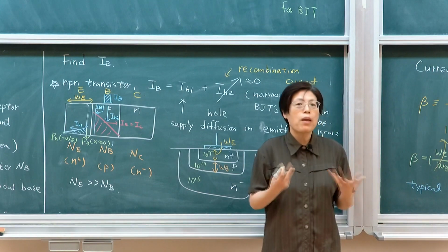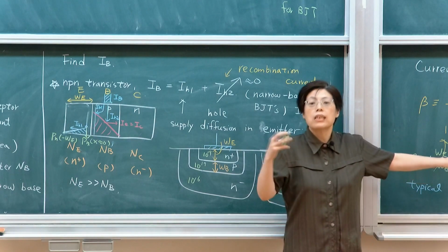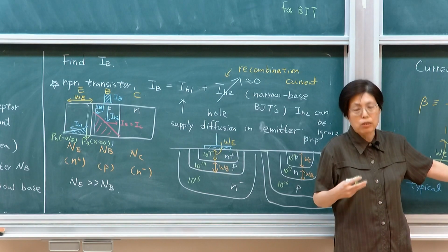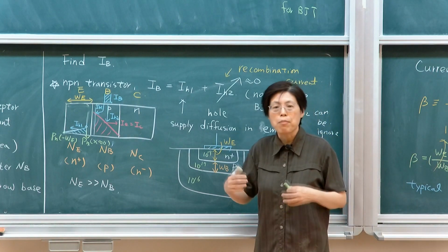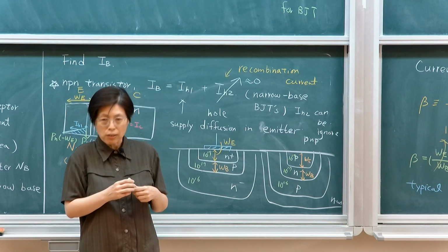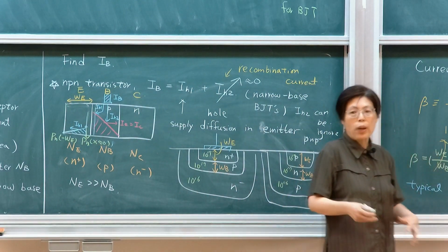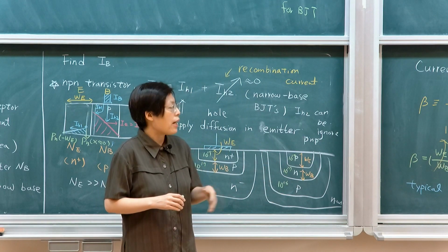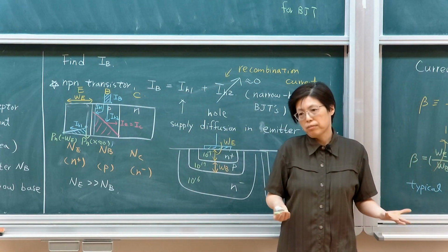And if you think about it, why does it depend on the ratio? This is because the main current that I'm delivering is electron current. Collector current is electron current for NPN, and the base current is hole current. Therefore, you use these two ratios. If I'm doing a PNP transistor, my main current will be hole current, and the base current will be electron current. So it will reverse the type, so your ratio will be counter, it will be 1/3. So you actually degrade the gain by 4 times to 9 times. Meaning that for the same structure, if I'm getting 100, the other will be 25.